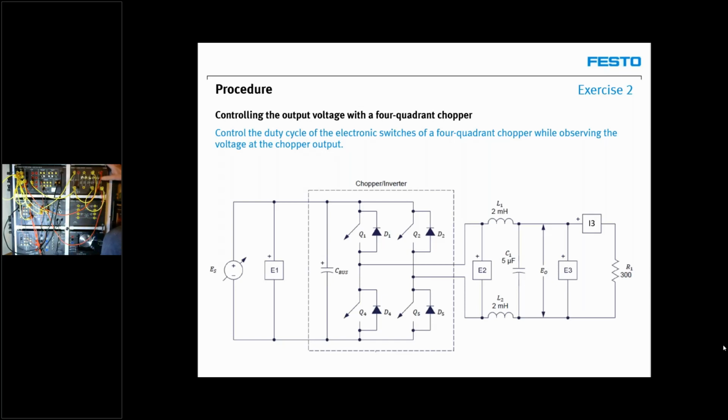So I make sure that my resistor is at the proper value, 1200 ohm. That does not fit, in fact, what's there because I don't have the same voltage at the input. My capacitor is set to 4.4 microfarad, which is the closest I have to 5 microfarad of the circuit. And my inductor doesn't have any control. Good. Let's start the power here and go back to our LVDAC software.